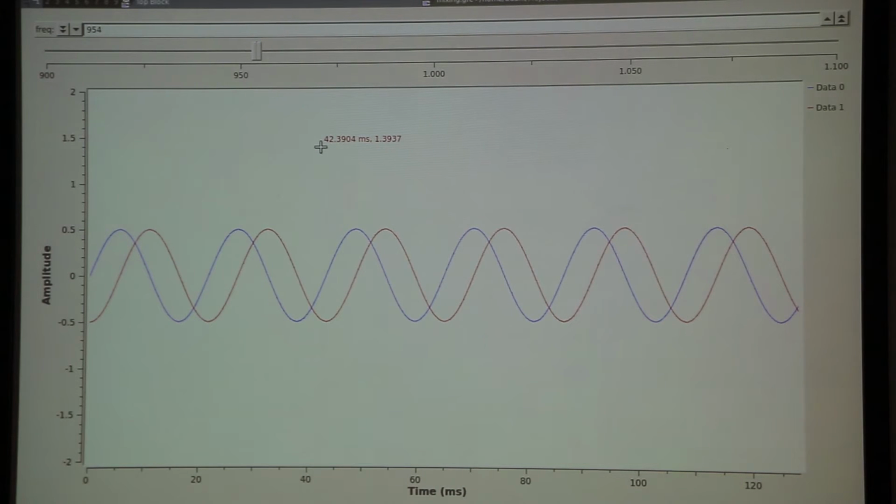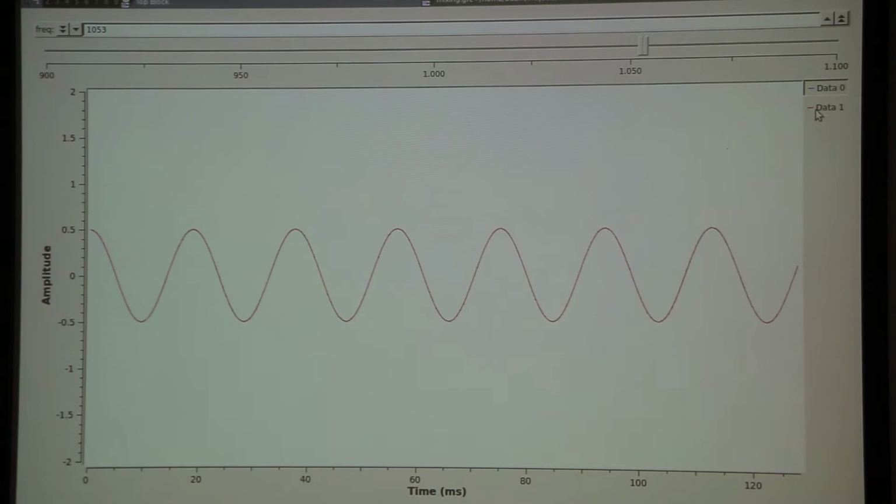And it basically comes down to the fact that if it was a negative frequency originally, then you'd get this red, which is the phase-shifted local oscillator, coming a bit after in time the blue, which is the non-phase-shifted local oscillator. Even if we were just looking at the red one, the new shifted one, we still can't tell apart the positive or the negative frequencies. It's only when we have both that we can see which way around it was.